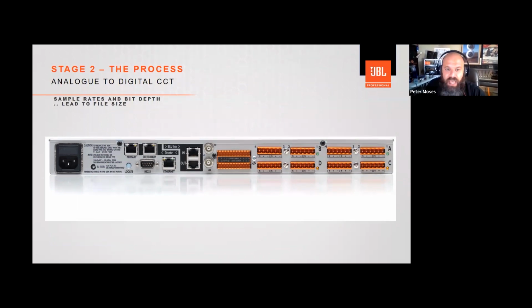Now let's look at that in practical terms. If I have a digital audio source, there are up to 6 different places I can interact with it on HARMAN's BSS Blue 806DA. If the audio adheres to the Dante protocol, I can send it to my processor via the primary port. What's important about this is that I can transmit and receive audio via this one connection.